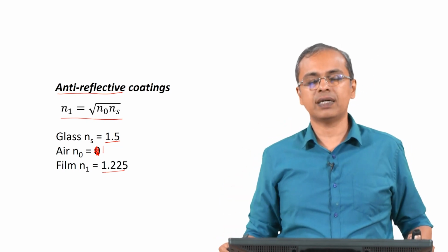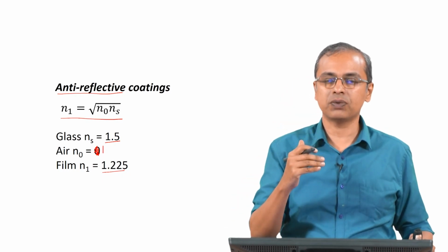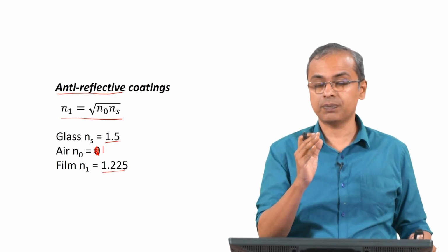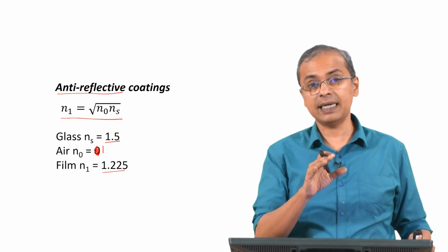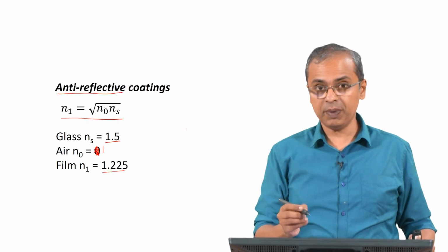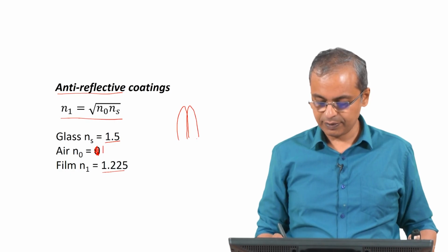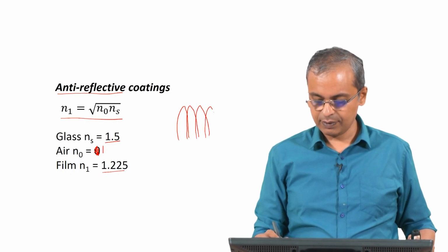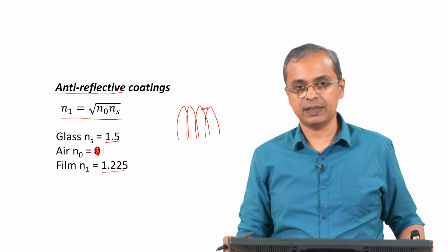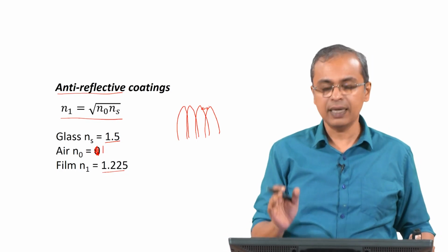So, these kinds of anti-reflective coatings are worked on. In fact, in this context a lot of work is done even with respect to say biomimicry. So, for example, people look at the eyes of moths and those are considered very non-reflective, and there it is done with respect to structure. So, to mimic that you will have a series of structures that look like this, which are very closely spaced, and closely spaced in the sense that this spacing should be of the order of the wavelength of the radiation that you are looking at. So, there are some specific calculations that you have to look at, but it is in that order.